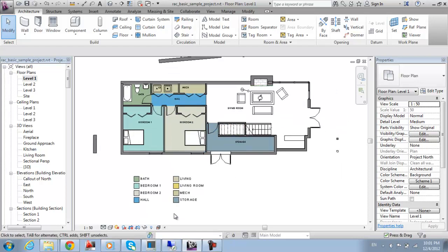So the first thing I want to describe is the architecture of the Revit elements. Look, as you see inside here, doors, single flush, and 820, 2100. Okay, look, this one is called a category. If you look here, this is the category of wall, and basic wall is the family name. Generic 200 is the family type.